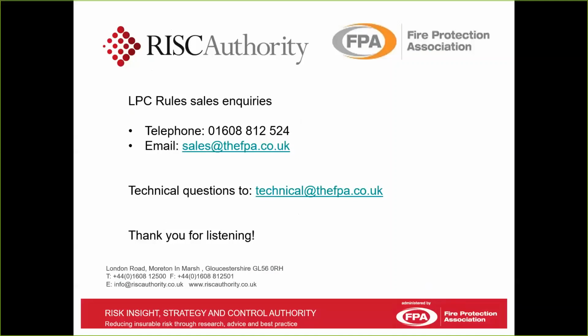Commentary and recommendations regarding this air being trapped. There was a question mark about whether the air wouldn't be vented when the sprinkler heads operate on a gridded system. Well, yes, they will do in the operating ranges, but not in the non-operating ranges, as I explained in this webinar. So there's absolutely a need to vent those. So that's some of the questions that we've had so far.